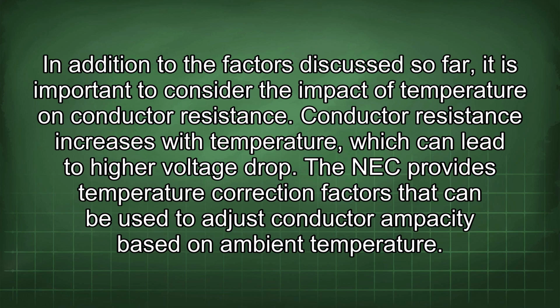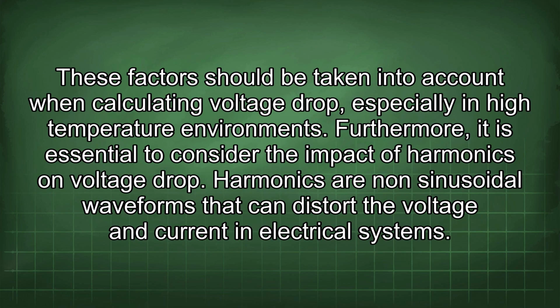Conductor resistance increases with temperature, which can lead to higher voltage drop. The NEC provides temperature correction factors that can be used to adjust conductor ampacity based on ambient temperature. These factors should be taken into account when calculating voltage drop, especially in high temperature environments.